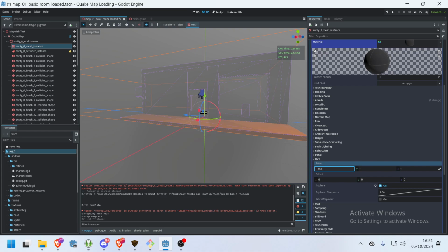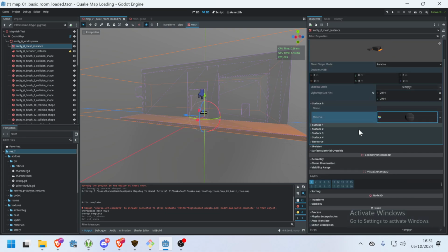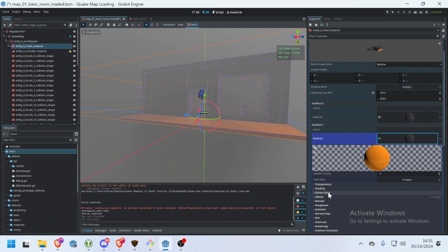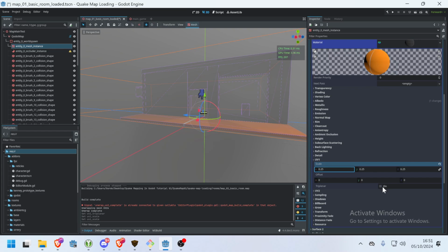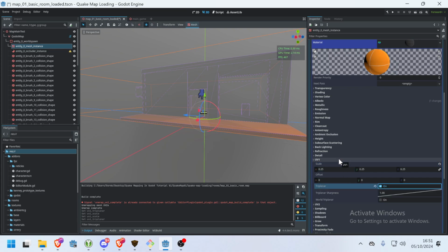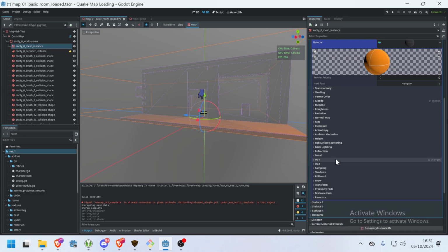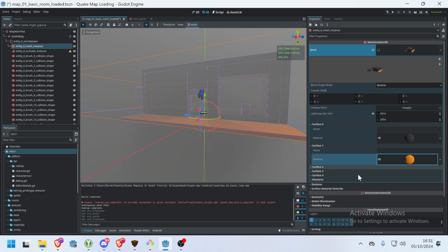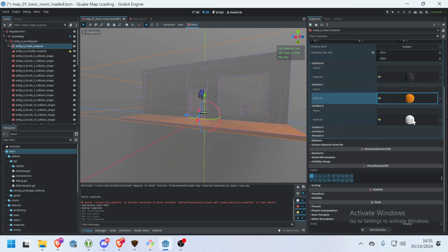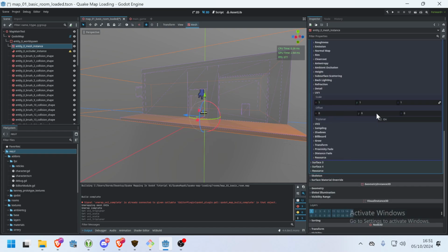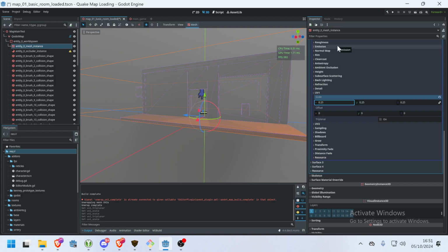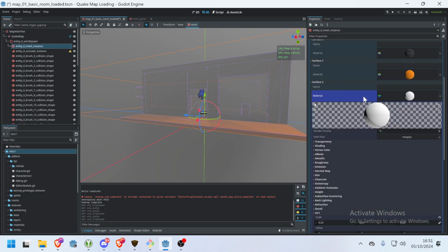0.25. If you're wondering why we use UV1 and not UV2, UV1 is what you see, UV2 is the light map in this specific example. The light map is used for the light mapper, so the light mapper reads and writes the lighting data there, I believe.